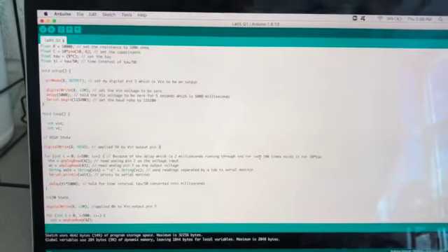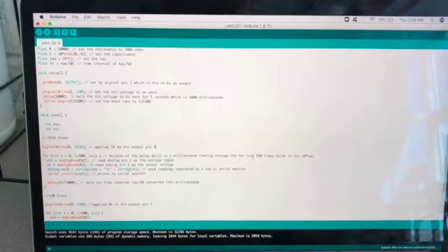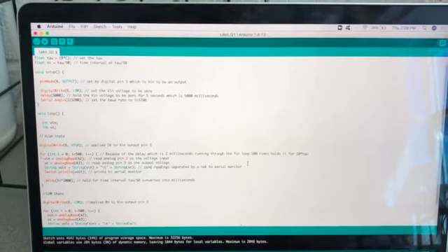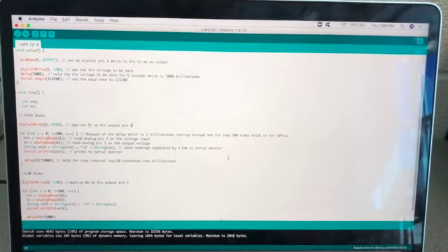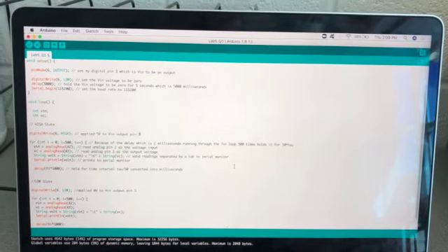Here's my Arduino code. In the setup, I declared pin 6 as an output, set it to 0, and held it for 5 seconds. Then I set the baud rate. In the loop, I set pin 6 to high and ran a for loop that holds this value for 10 times tau, which came out to be 1,000 milliseconds.